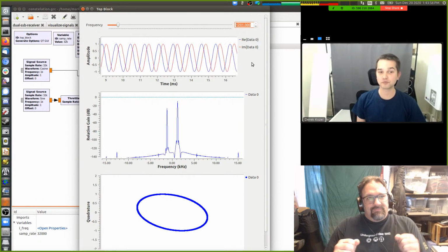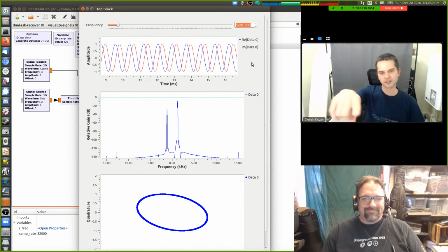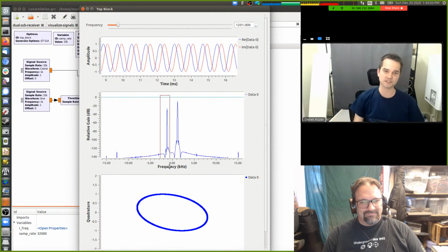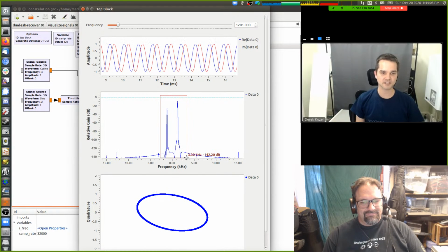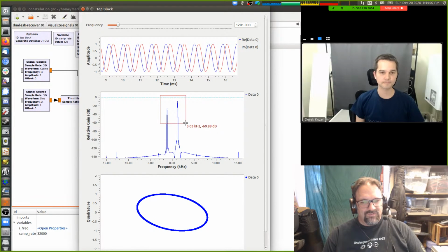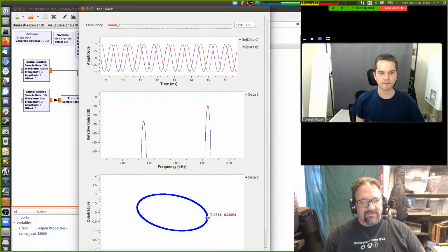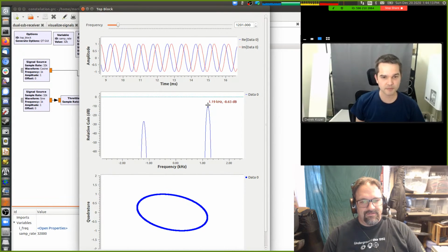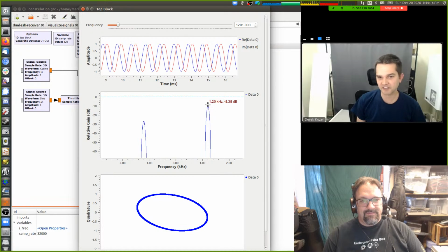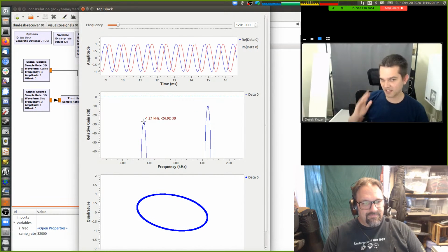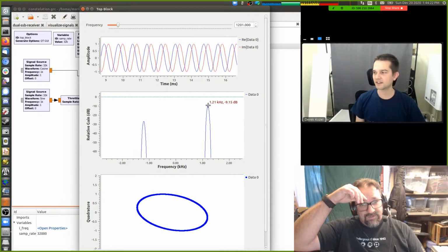And while it looks really strong here, Mark, can you zoom in, like click and drag a box over the two peaks, only down to like -60 dB or something? Over down to -60, like that? Yeah, something around there. So we can see that one of them is at -8 dB, and the other one's at -28 dB, around it.